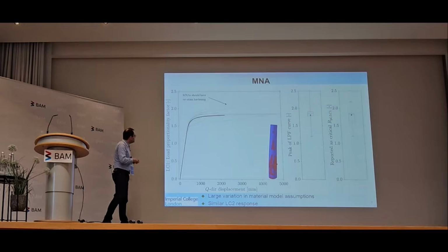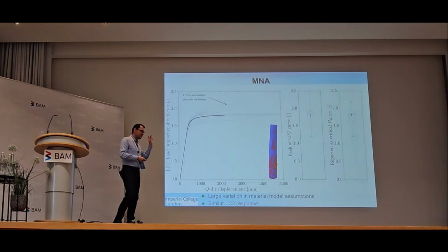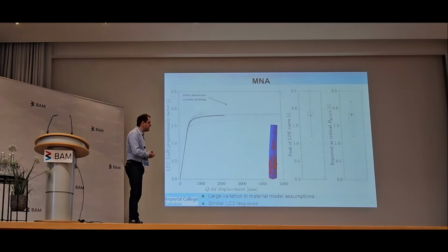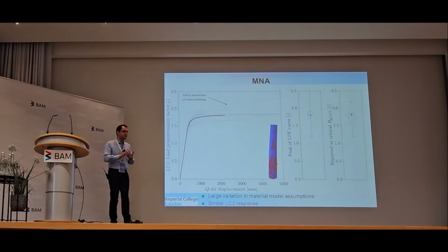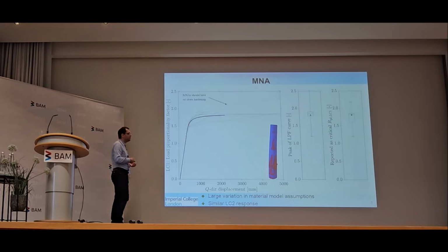So what I see here, in an MNA, you apply your load set. It's not an eigenvalue analysis. It is a nonlinear path tracing analysis. Because it's geometrically linear, there is no scope for buckling. You will not be buckling here. What you want to get is full plastic collapse. So it's the idealized reference full plastic collapse state. As you increase your load, initially you will have a complete linear elastic response, but eventually somewhere begins to yield. And so your equilibrium path will begin to drop in gradient a bit.